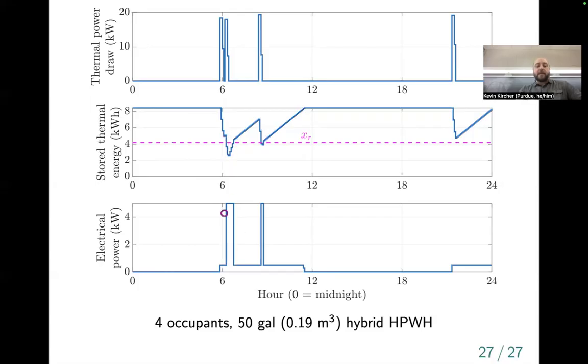And then as soon as we begin to drop at all, we turn on the heat pump, which is the low power here, about half a kilowatt of power consumption. And then when we get below this danger threshold, where the water's getting very cold, we turn on the backup heat as well. So we get about 5 kW: 4.5 from the heating element plus half from the compressor.